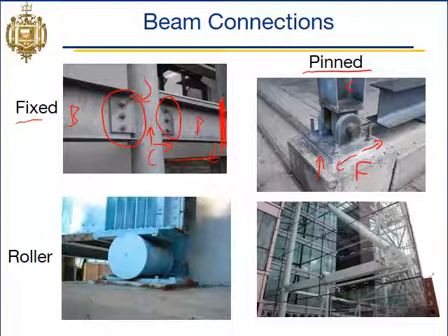But we see we got this big bolt here. So this connection does allow this to rotate this way or that way. Depends on the structure. Maybe the structure is fixing it higher up, but at the connection here, this can rotate. This is a great type of connection when you're doing steel structures, because it allows you to connect it to the foundation and then lift that piece up. So you can connect it while in a laying down state, and then lift it up and connect other pieces to it.